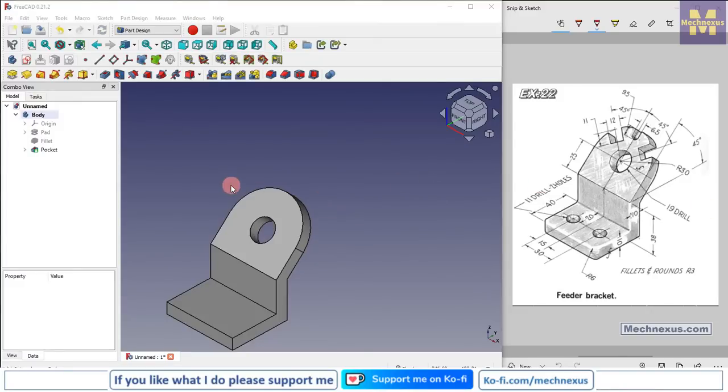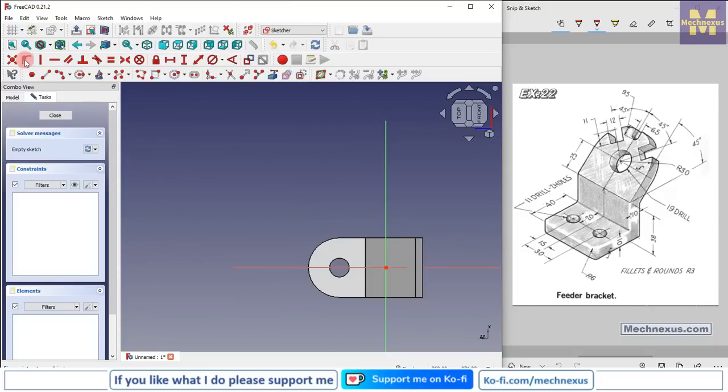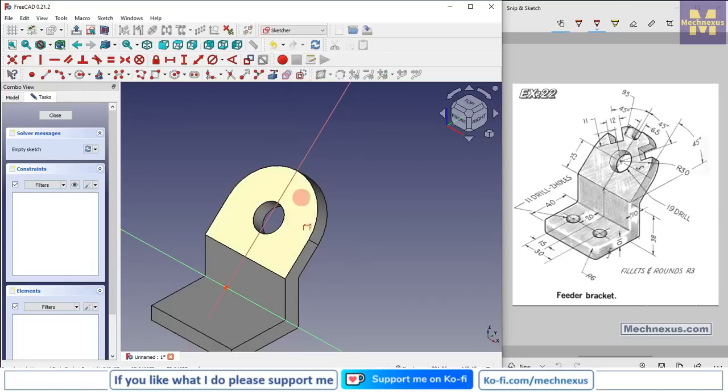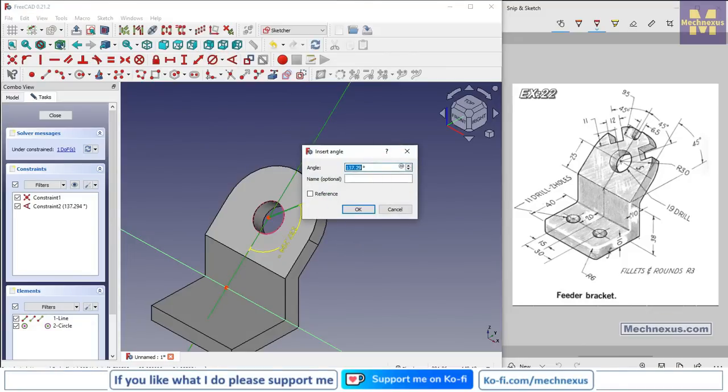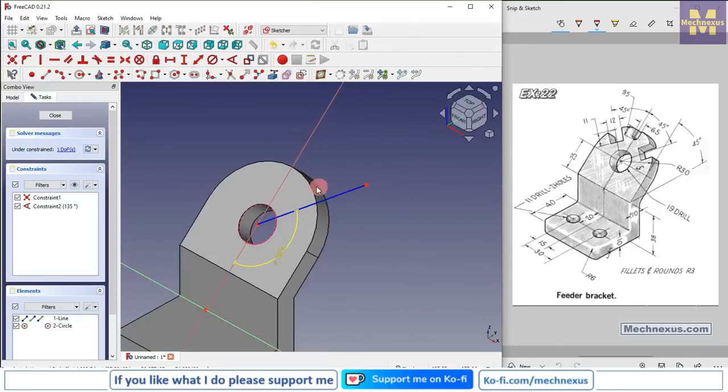And now we will select this face and we will create a construction line at 45 degrees, and then we will create this cut and then we will mirror it. So click on the sketch, and here we will switch to the isometric, and we will click on the project geometry and create a line, and from here select angular constraint, select this and this, and provide it 135 and select it and make it construction.